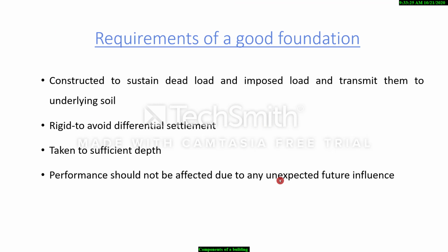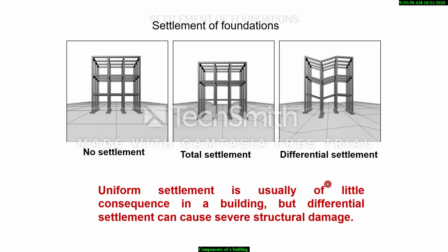So what are the requirements of a good foundation? The foundation should be constructed to sustain dead load and imposed load and to transmit them to the underlying soil. It should be rigid enough to avoid the differential settlement. It should be taken to sufficient depth for the proper transfer of the load to the ground. Performance should not be affected due to any unexpected future influence. It should be properly designed.